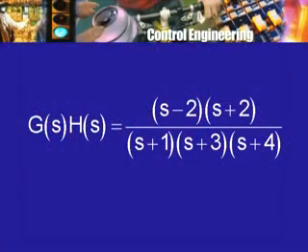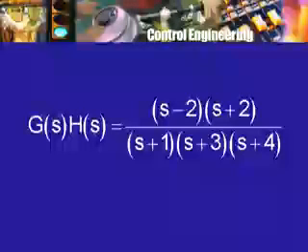So, here is the loop transfer function that we had looked at earlier, and henceforth we will use s in place of z. Now, if you remember, what we were looking at was the overall transfer function T(s), which was given by G multiplied by K, of course, the gain, divided by 1 plus K GH. This was the overall transfer function of a closed loop system with a transfer function G in the forward path, a transfer function H in the feedback path, and a gain K preceding the block G, and this K in general corresponds to some kind of an amplifier gain.